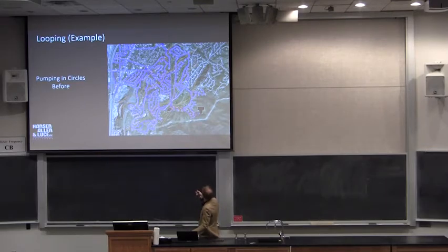So I'm going to trace where this water goes, put a little Kool-Aid in this pump station, and this pump station is triggered by the level in the tank. So the level in the tank gets low enough that the pump turns on, and here goes the water to fill the tank. But what they didn't realize is that water kept going down, and within 1 hour, this water was coming back to the intake of the pump. So they're actually pumping the water that had just been pumped an hour before, and nobody was using that water. That energy was being wasted through what they call pressure reducing valves, or PRVs.